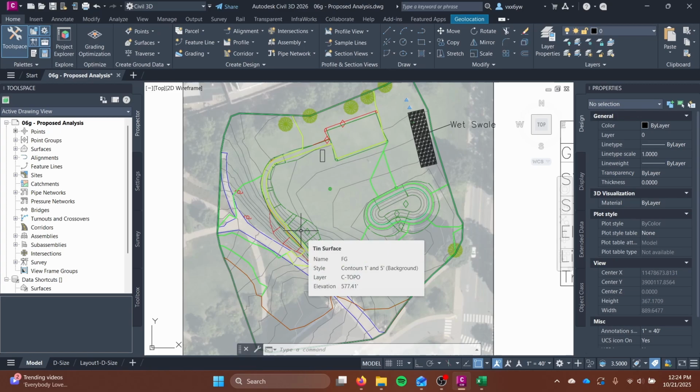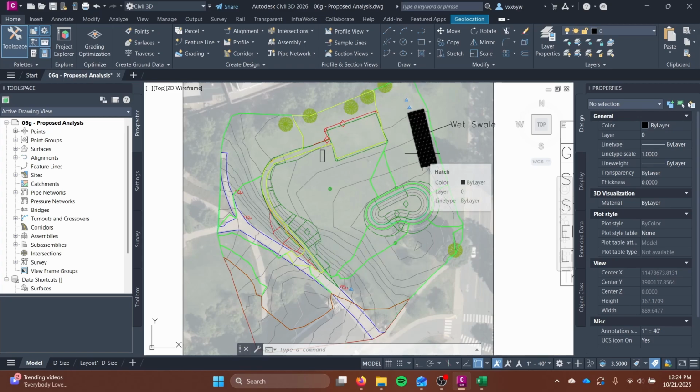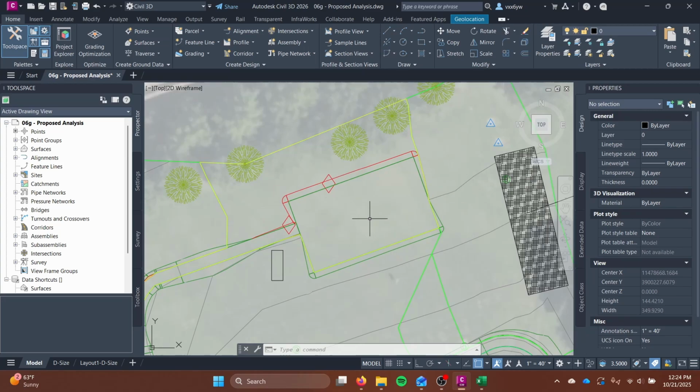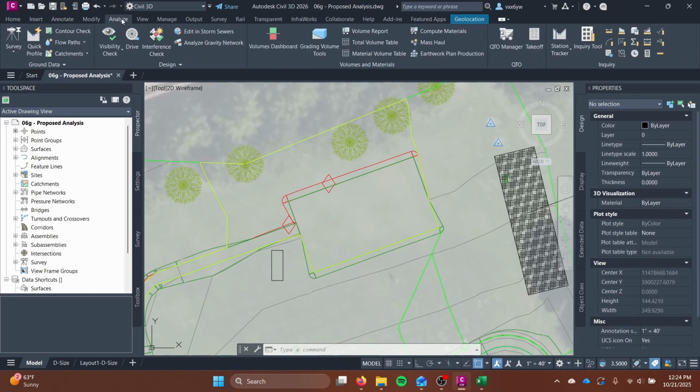So make sure you have a boundary defined for all of them, the flow path for all of them, a coefficient that makes sense. So now your area is going to be smaller, your coefficients will be different because you added things like your BMPs, and we're working with things like pavement or a roof system here. So keep that in mind. For the roof system here specifically, since this is a flat area, you will not be able to turn this into a catchment. And I can show you what that might look like and why that's true.